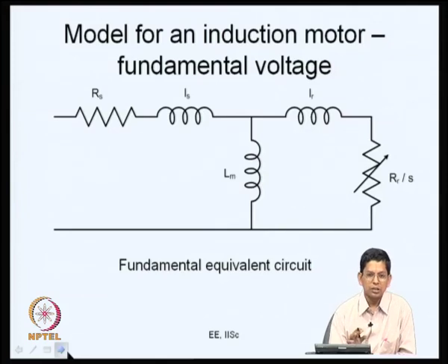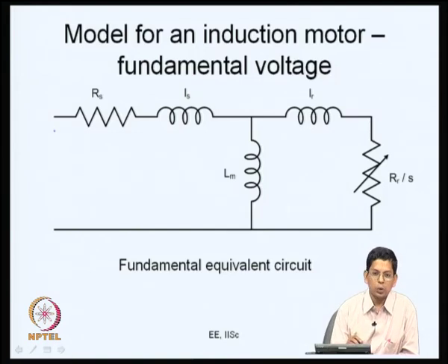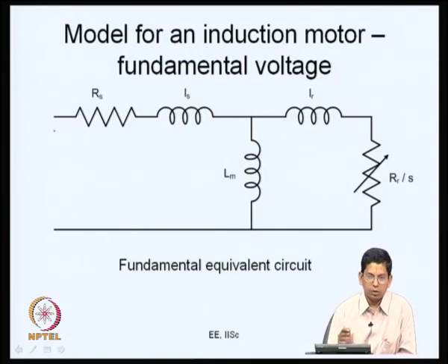Now, this is all a kind of review of Fourier series, so that we can use Fourier series effectively to calculate the fundamental voltages and harmonic voltages of several different PWM waveforms. The next issue is, when the harmonic voltages are there, what are their effects? What gets applied to an induction motor fed from a voltage source inverter is not only the sinusoidal fundamental component, harmonics also get fed there.